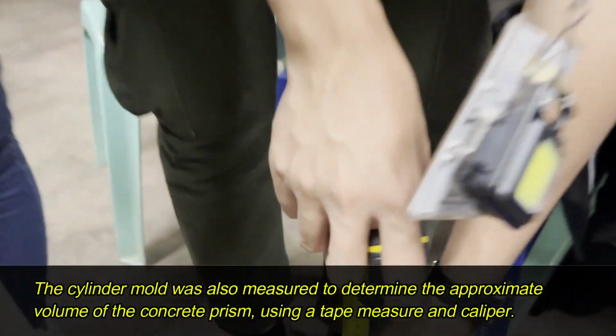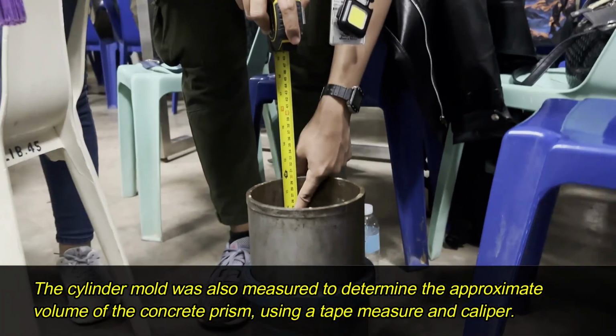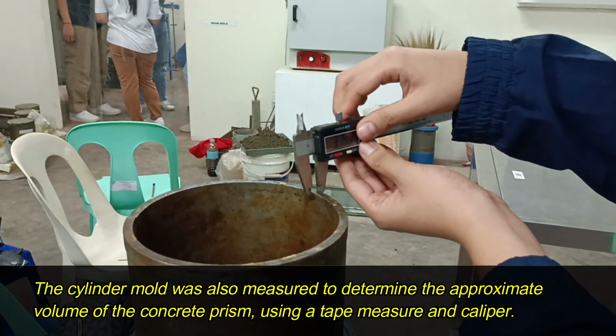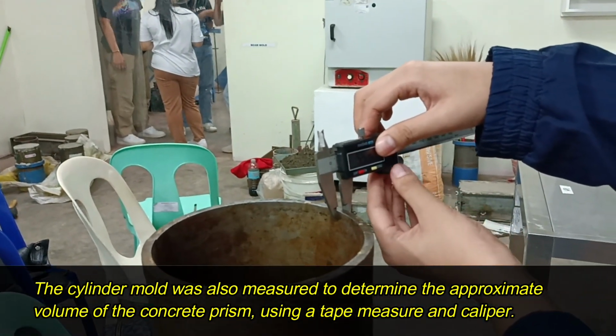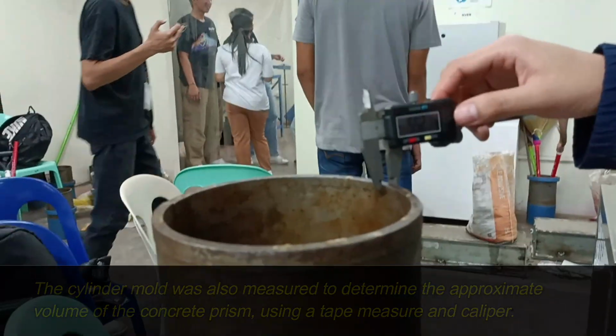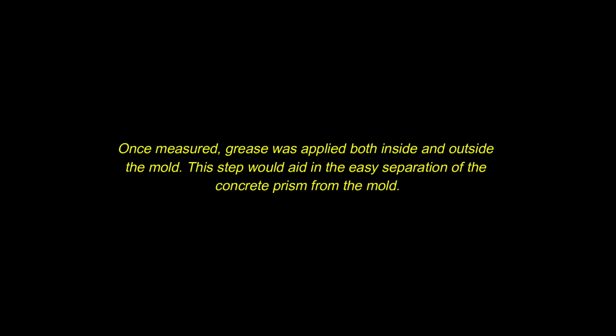The cylinder mold was also measured to determine the approximate volume of the concrete prism using a tape measure and caliper. Once measured, grease was applied both inside and outside the mold. This step would aid in the easy separation of the concrete prism from the mold.